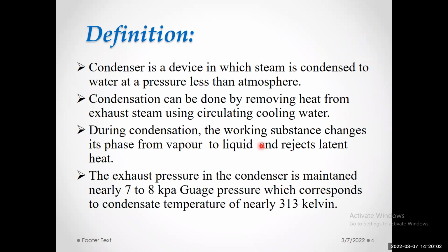So during condensation, the working substance changes its phase from vapor to liquid and rejects latent heat. The exhaust pressure in the condenser is maintained at nearly 7 to 8 kilopascal. So it is below atmosphere.